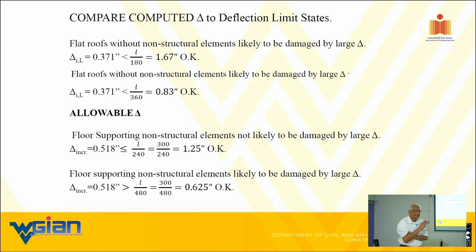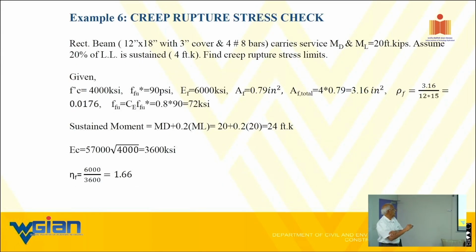That is tied to the human response, 2 to 3 hertz. So either it should be below 3 hertz or above 6 hertz. Between 3 and 6 hertz, things come close to resonance. They don't resonate, they come close to it.